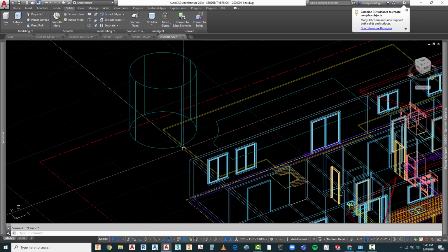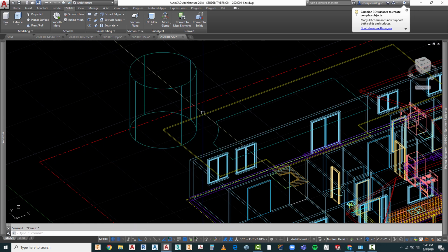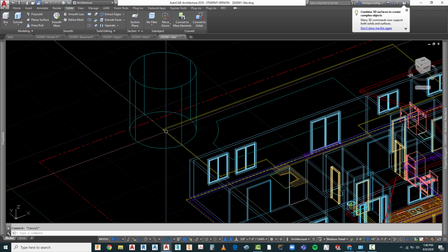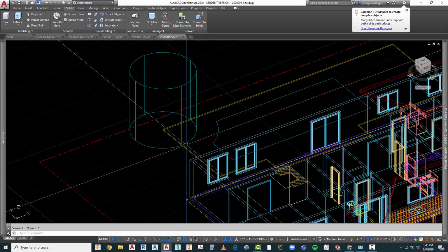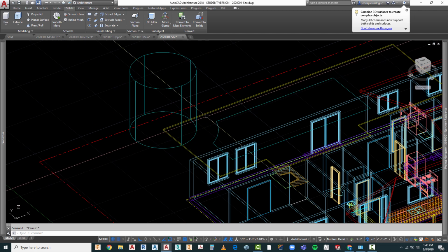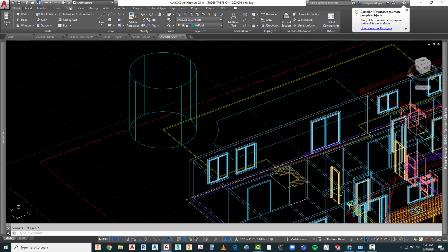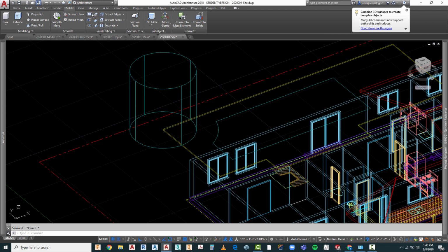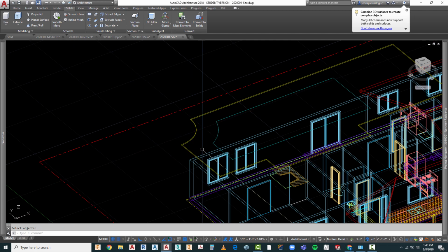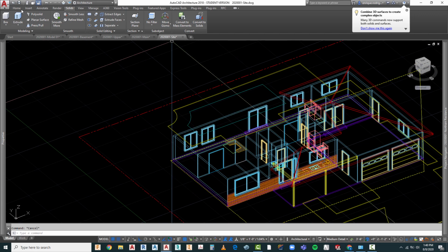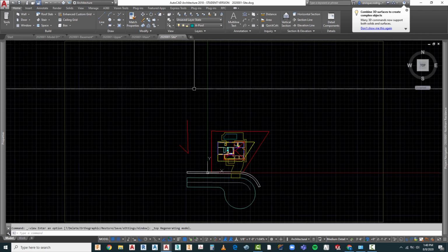That really doesn't matter. The only thing I have to be aware of is that when you do a Subtract command or you do a Union command, you have to worry about what layer it's going to be on if these two are on different layers. So let's see what happens. If I go back to my Solids tab and, rather than this Union, I can go to Subtract. I'm going to select what I want to subtract from, and then I'm going to subtract this one, hit Enter, and there we go, I've got my cut. Let's go back ahead and get back onto the top view.